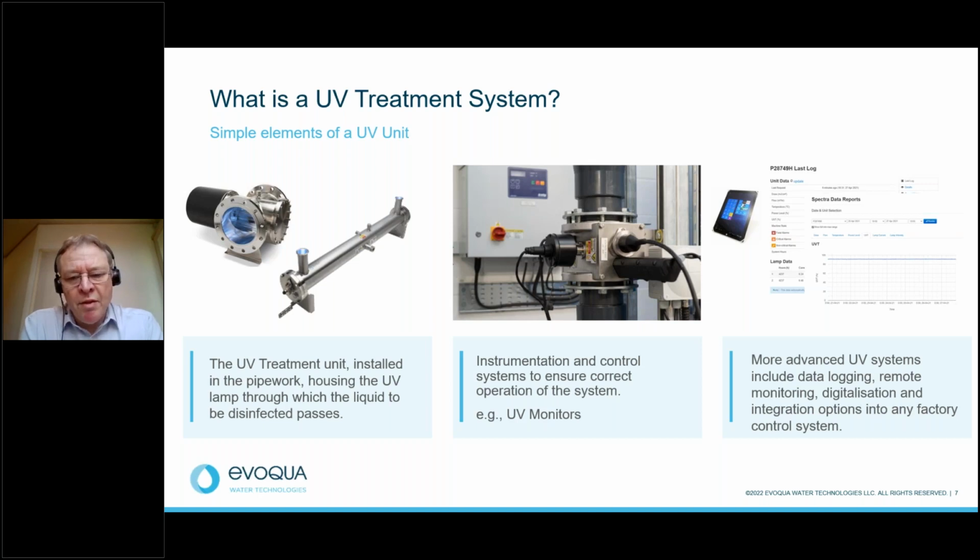disinfection applications. So, for example, a unit on a 4-inch piping line would typically connect to a unit with a 4-inch connector. So they are generally sized to the pipe, and that is really a result of the dose calculation, generally speaking, the dose you're looking for in most applications. So the UV chamber itself houses one or more UV light sources, which are isolated from the water in a highly refined quartz sleeve.